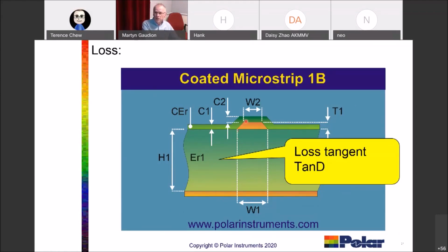Then at lower frequencies, for the copper losses, the current's traveling in the whole of the copper trace here. But as the frequency increases, gradually the current travels out to the surface. So you've got an increasing loss because the copper is carrying the current only on the outer surface of the trace that I'm outlining with the pointer here. Just the very outline carries the current. And then above that frequency, you start to increase that more.